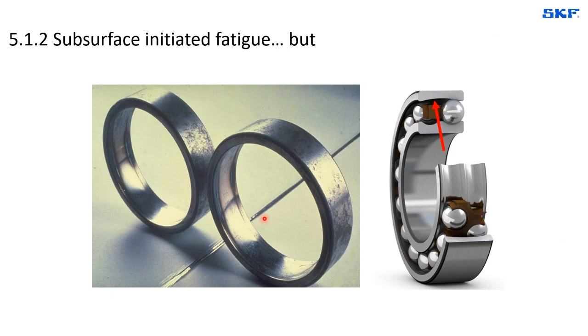So the reason why we are representing this case here with an oval housing, so the bearing has been squeezed into areas that are 180 degrees apart, is because the subsurface fatigue is a consequence of the level of stress on the material and the number of cycles, which are the number of times the balls or the rollers are going through that area with high stress.